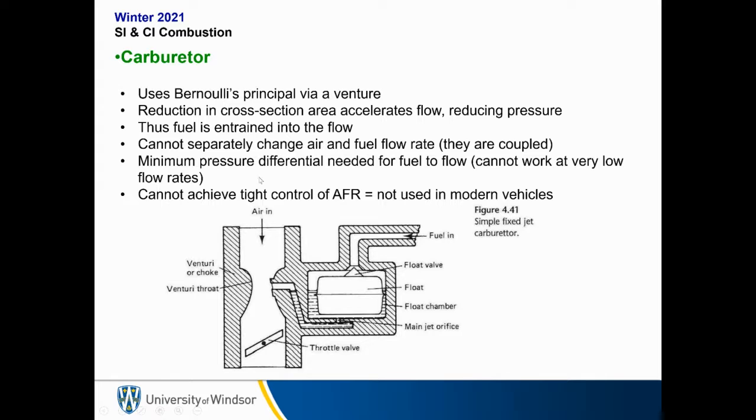Now the problem with this whole carburetor design is you cannot separately change the air and fuel flow rate. They are coupled. If you have less air coming in, you have less fuel. You can't decouple them to change the air-fuel ratio. Also, there's a minimum differential pressure needed for fuel to flow. In other words, this can't work at very low flow rates. So there's kind of a minimum that has to be flowing.